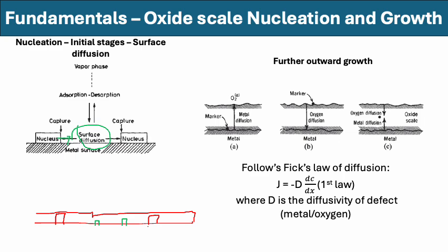I think this kind of example is taken with an example of nickel copper, where thermodynamically you can form both Cu2O and NiO on this nickel copper alloy surface, but because nickel oxide grows faster than the Cu2O, you generally get NiO scale with discrete islands of Cu2O which is embedded within this oxide scale. So that will happen.